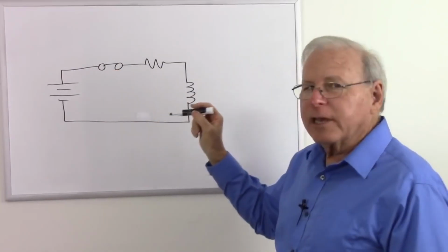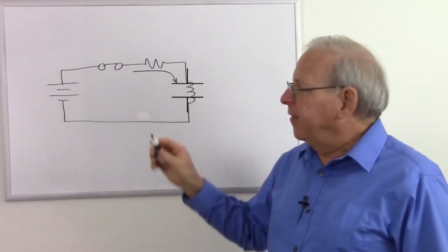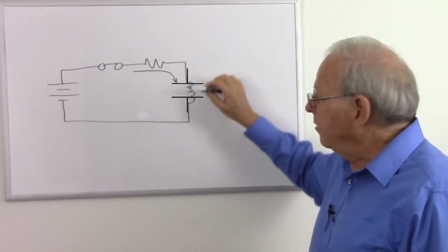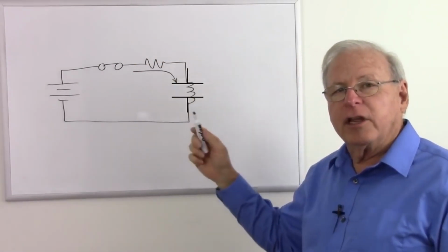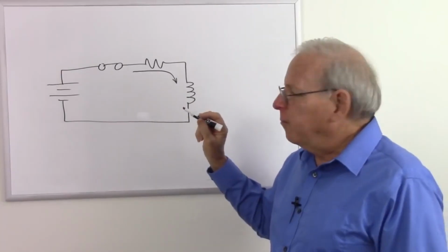And what happened with the capacitor? I had a surge of current into the capacitor, and that built up charge on one of the plates, which drove charge off the other plate. So current went in, the same amount of current comes out, looks for all intents and purposes like a short circuit. What does the inductor do at that moment in time?